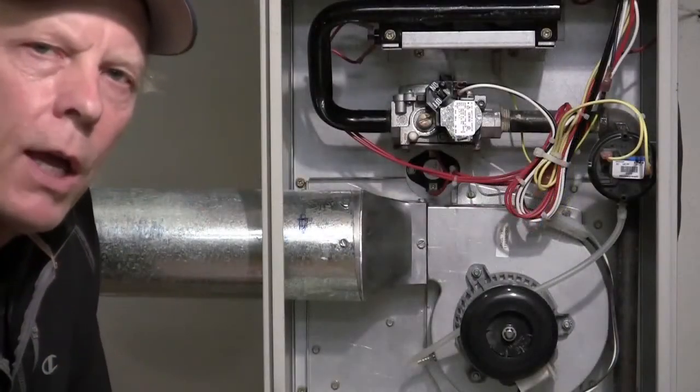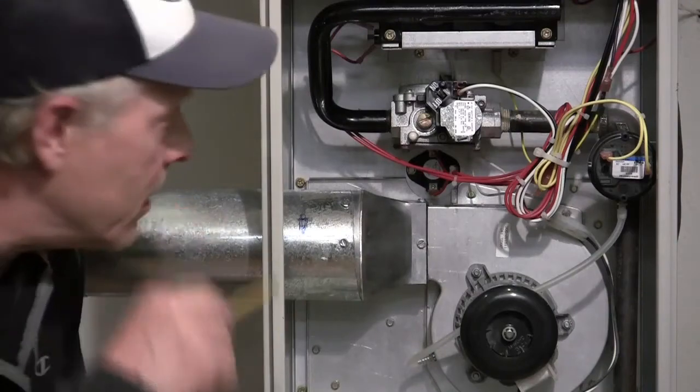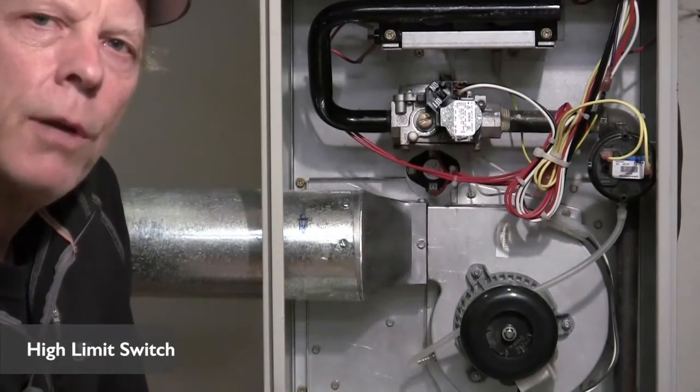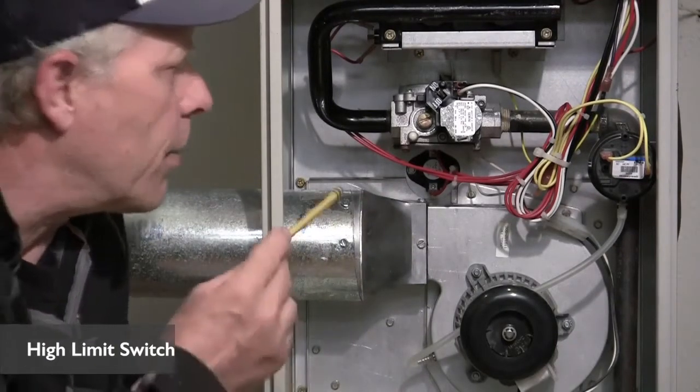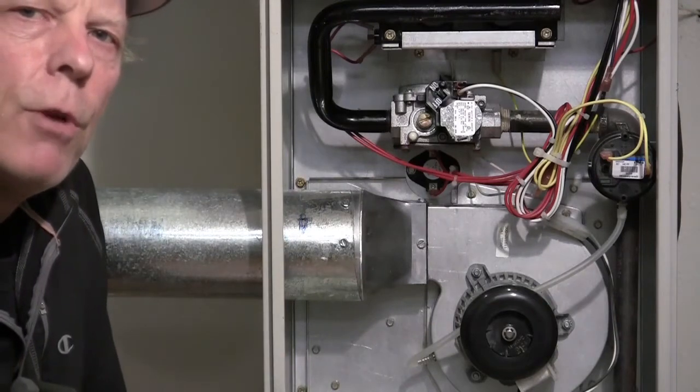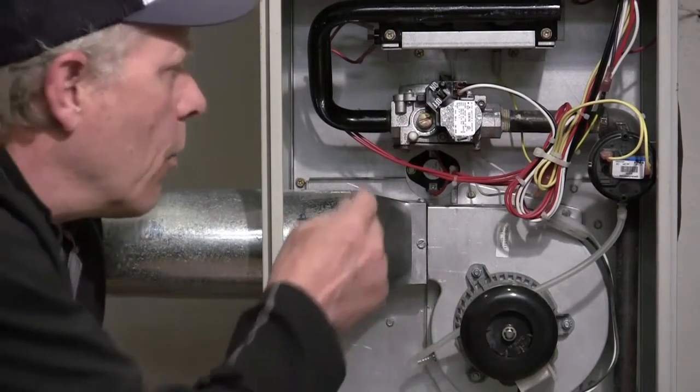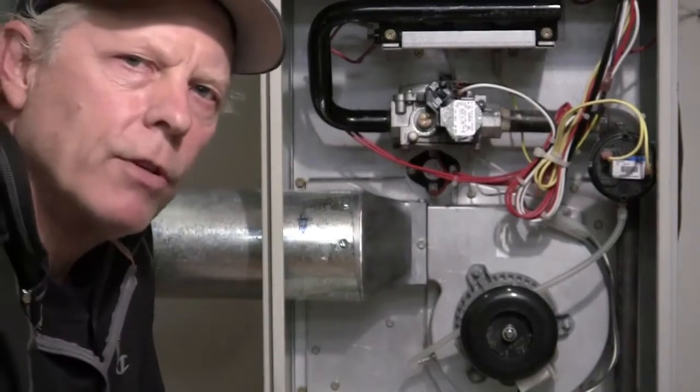Okay, on line 3, it asks the candidate to identify safety features related to the heating system. So I'm going to take a moment and zoom in so you can see closer. Alright, we're zoomed in now. We're going to take a look at our safety features for our heating system. The first one is the high limit switch. That's in the airstream of the house air, so if it goes above 250 degrees for any reason, maybe a clogged filter or the air handler breaks down or shuts off, we'd have too much heat back there, that would turn the gas off to the furnace.